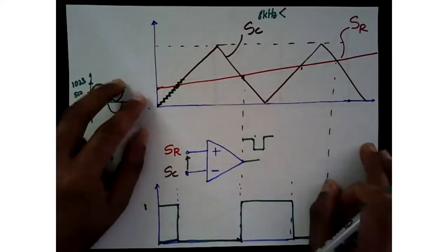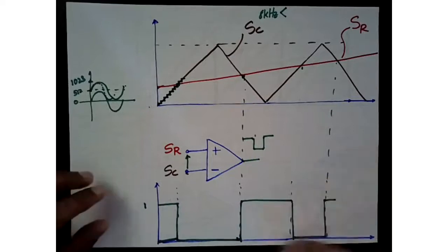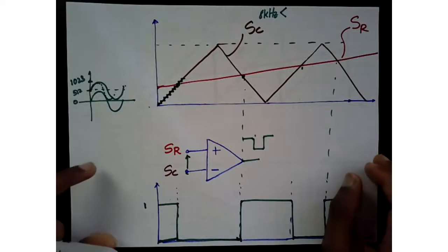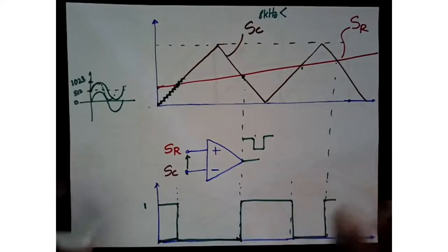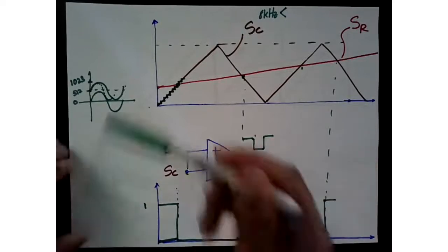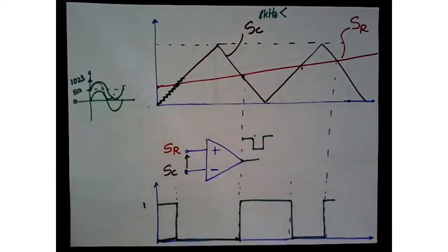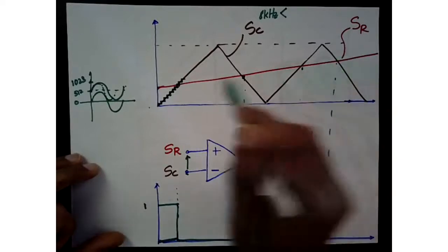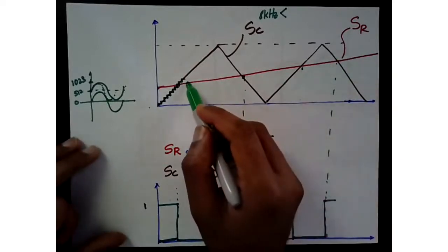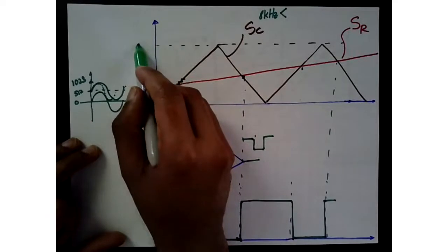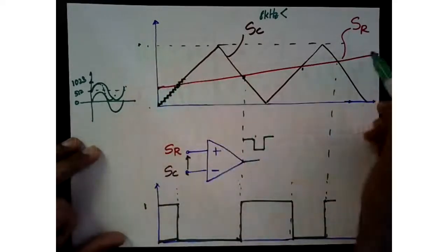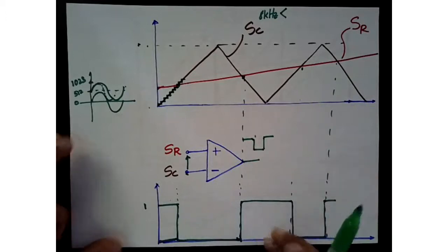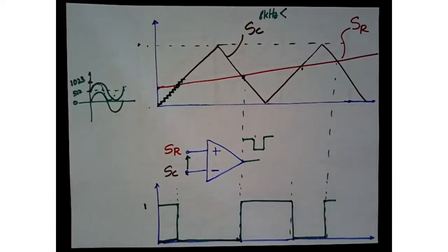Okay, and we'll see that in our simulation as well, because we want to generate a fine enough output voltage using the carrier wave. Okay, all right. And all of these are going to be implemented digitally. If you are using a microprocessor, it'll happen in the digital domain. So you have to pay attention to the maximum value of your reference signals, which will ultimately result in the PWM values.